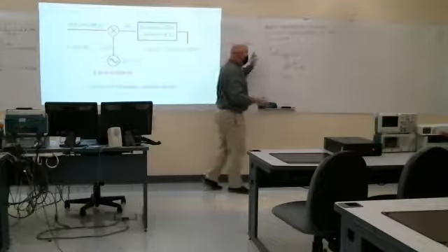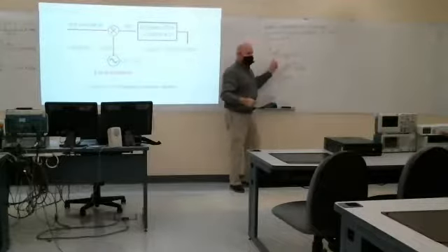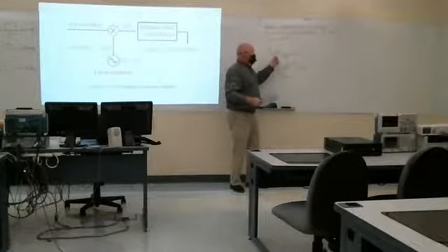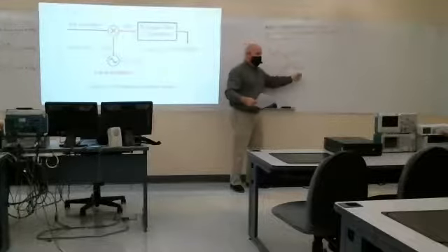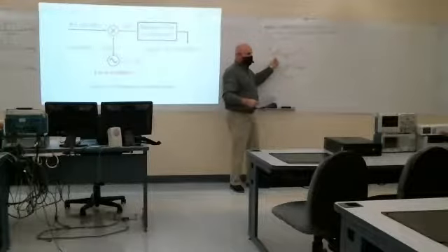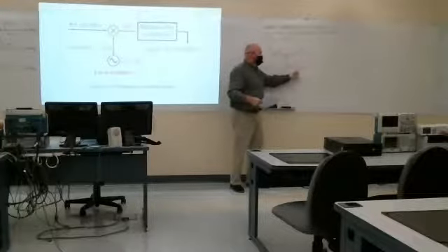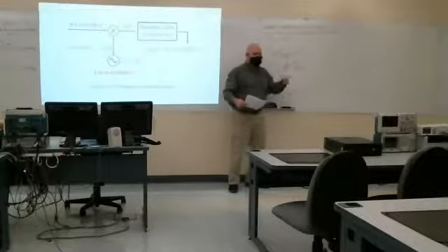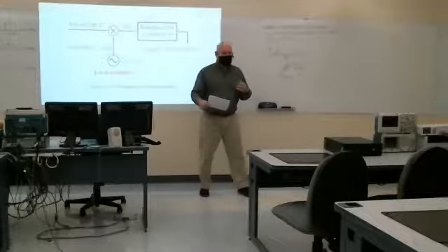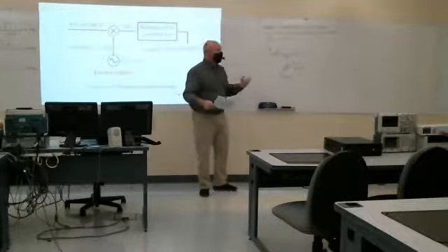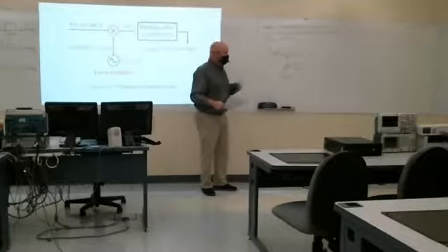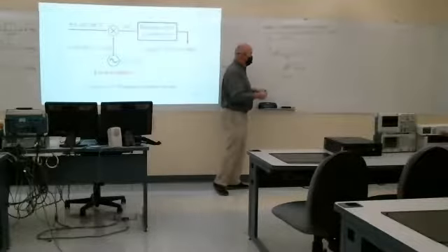But remember what we just had here, I said that if I want to translate f_C, for example, to f_IF, I just mix the station at f_C with another frequency that's f_C plus f_IF or f_C minus f_IF. Remember, we can use either. I just drew the plus here, no particular reason.